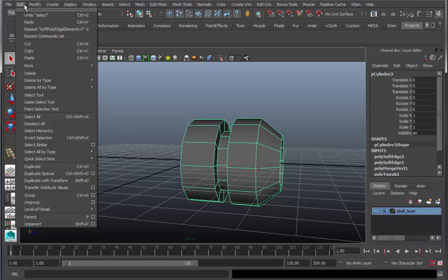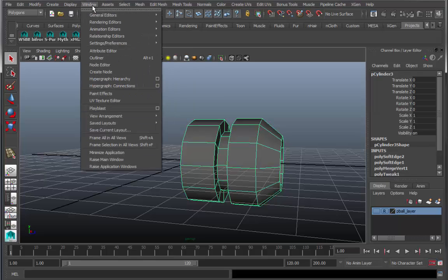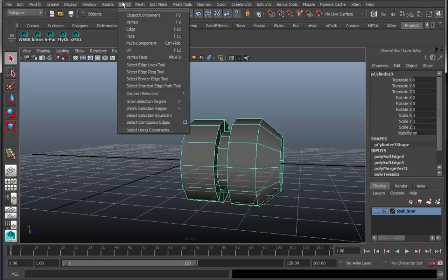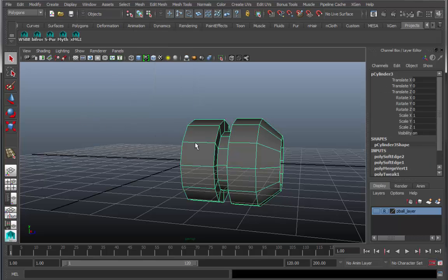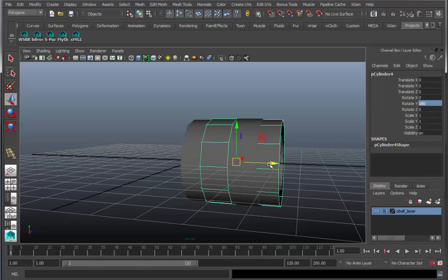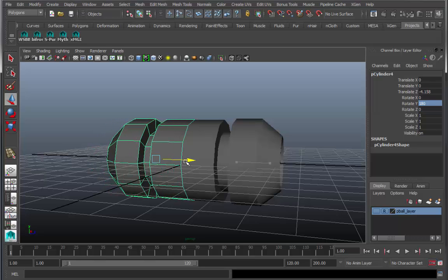And I'm going to utilize a method to create its doppelganger. I want to create a copy. Now I could duplicate it like so, just using the hotkey of Command D, and then flip it around by typing in the rotation in Y, and then moving it over until I'm sure that these two match up exactly.